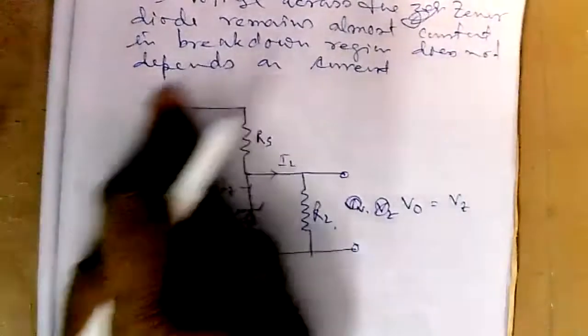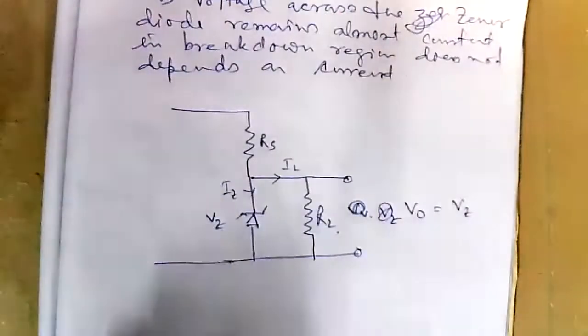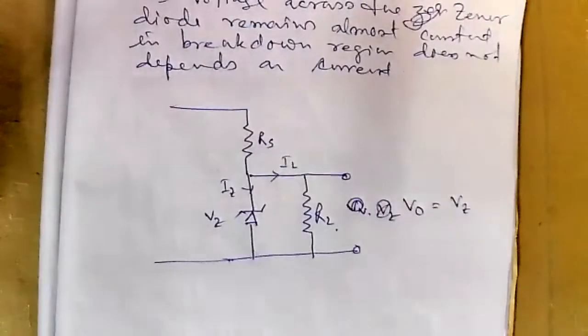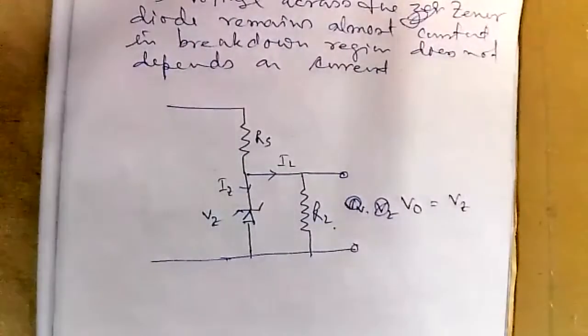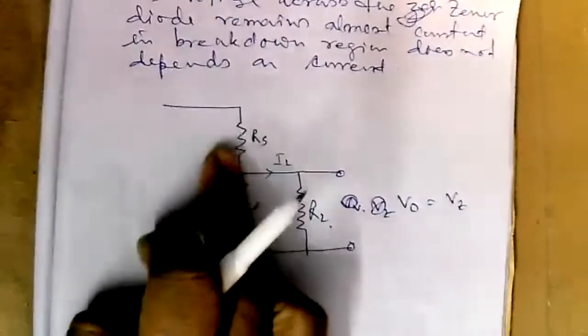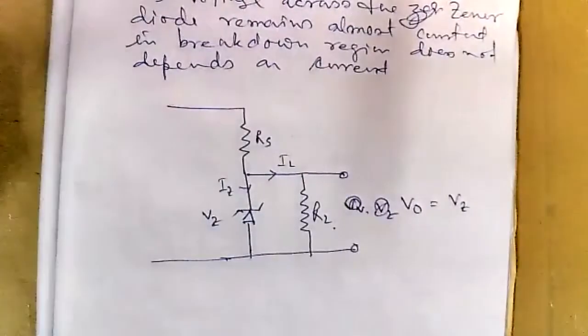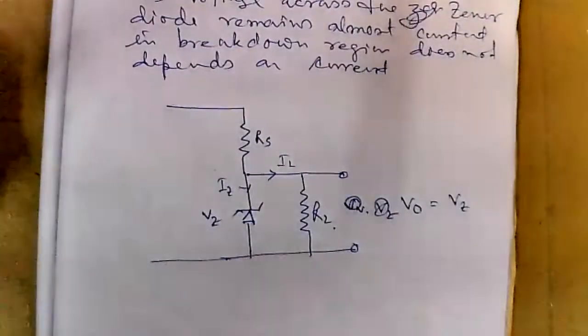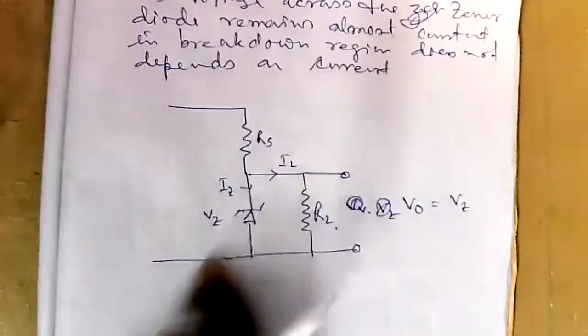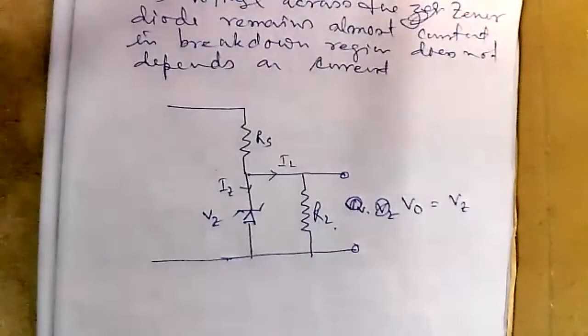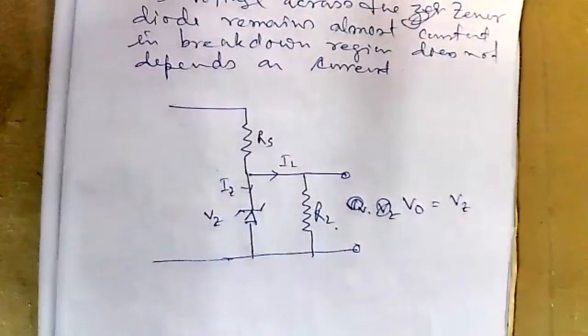Okay. So the DC current from the rectifier is coming. Now we need a constant voltage at the output. So what we will do, we will use a Zener diode in parallel with the load resistance. So whatever may be the current in the circuit, the current to the RL will remain unchanged. It always gives you the voltage drop which equals Vz. The extra current will pass through this Zener diode. Is it understandable?